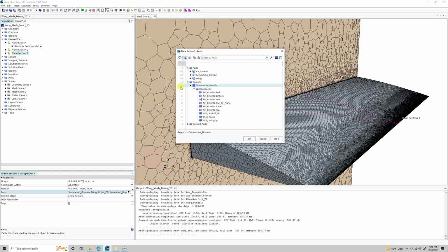It has a big box to the left, and two smaller boxes to the right. These all have specific meanings. What the big box means is that it is just selecting the volume that is the simulation domain. Not any of the surfaces, the volume.